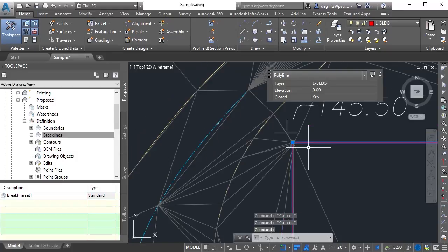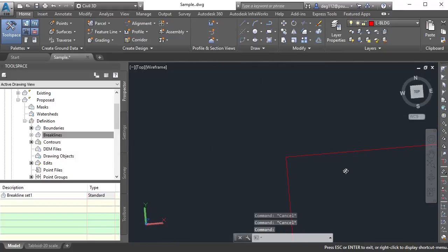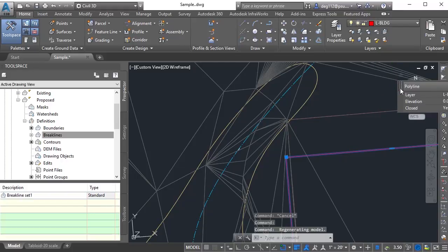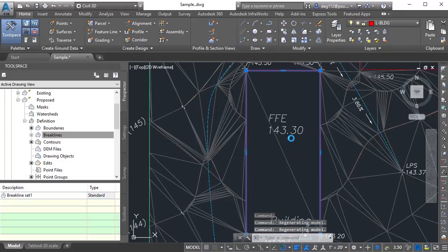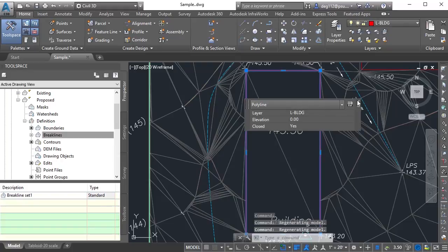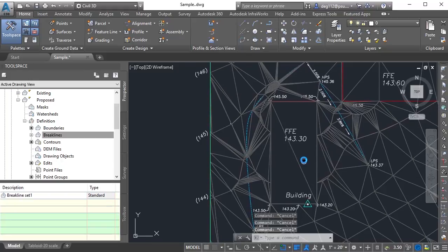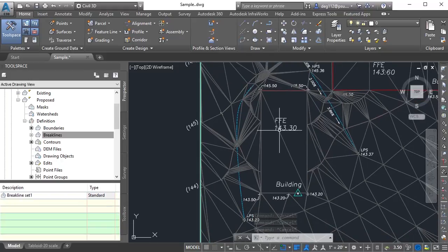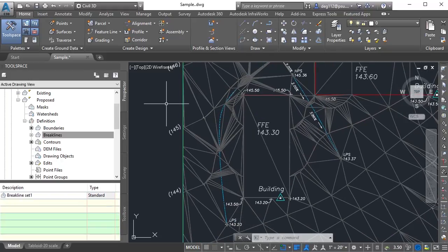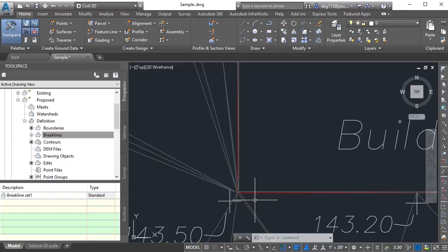Now you might think, oh, I can just set this to an elevation like I just did for my base. But I can't, because this piece, I'm gonna turn this dynamic off. The outside edge is not the same elevation. So I'm going to use a new object, and it's called a feature line, to create a line that runs around the top at the elevation.